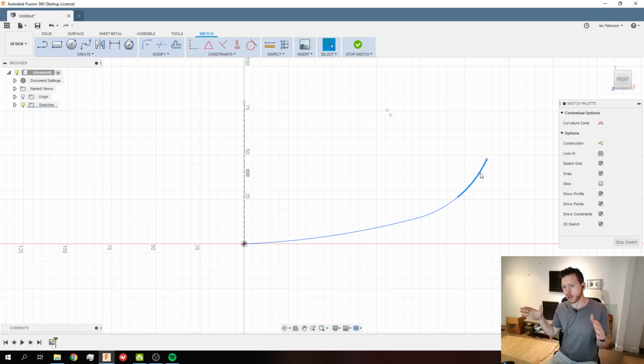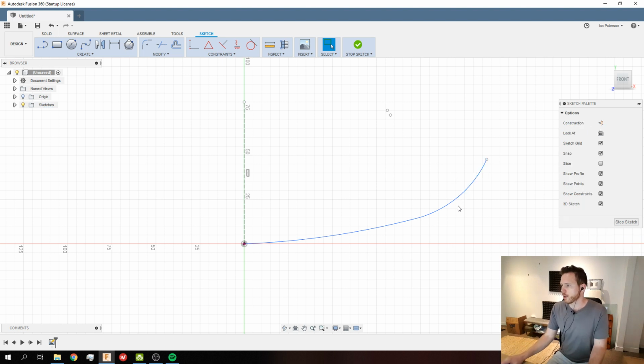So it's going to start out as a rectangle of wood. You're going to cut out the board from that, and there's going to be a little bit of overhang on that edge. Alright, so first thing to do is to define where your concave is going to be. Like the 18mm deep concave on a 9.75 inch wide deck is pretty normal, so I'm just going to define a couple of those points.